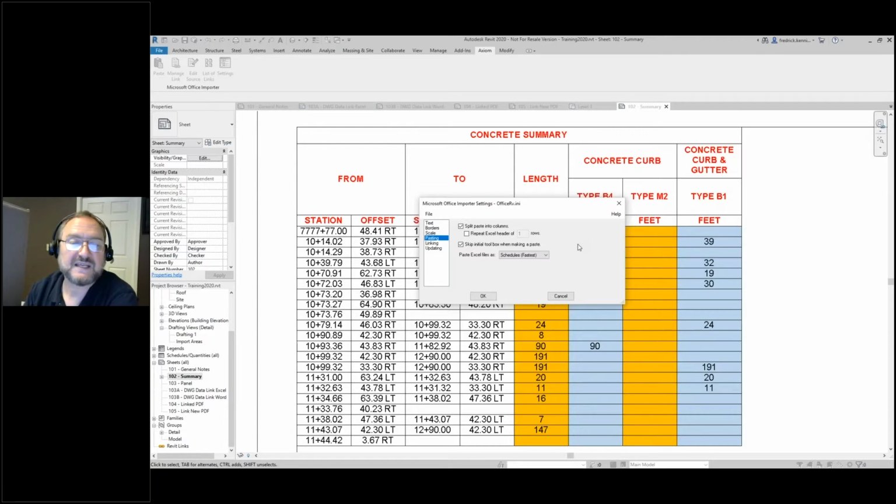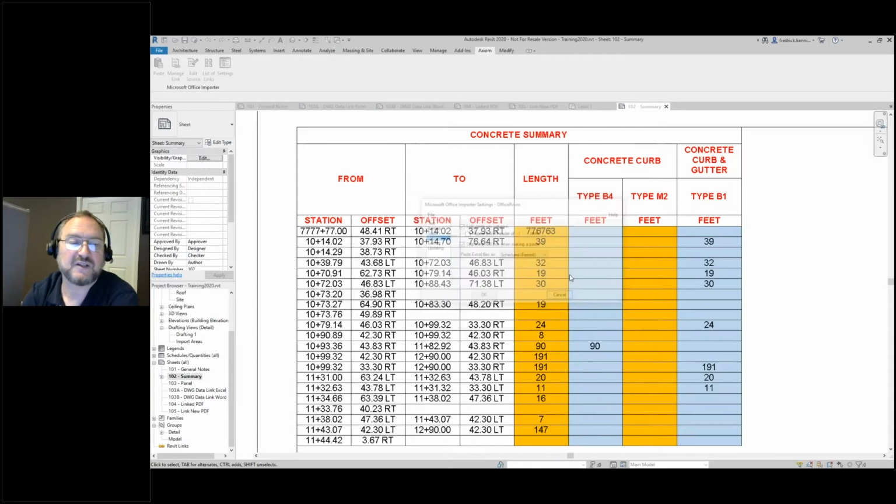Now, in both cases, because Word and Excel, no matter where I paste them, whether they're a detail group or, in the case of Excel here, a schedule, either way, it doesn't matter. If I give this project to anyone, I do not have to include the source file, and they're going to see the paste that I made. In other words, the pastes don't rely on the source file after I've got the data pasted in.